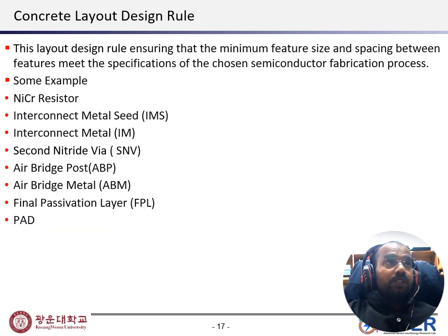Now, concrete layout design rules. These layout design rules ensure the minimum feature size and spacing between features that meet the chosen semiconductor fabrication process.